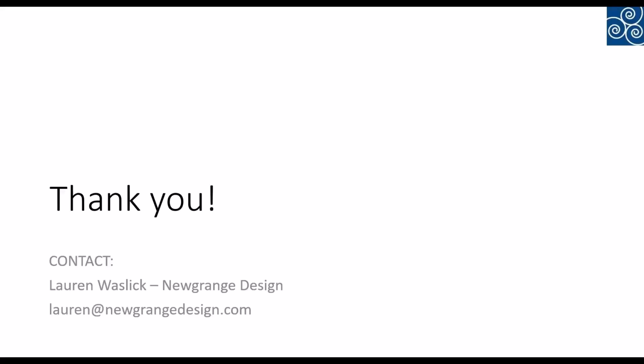What would be the smallest number of layers for a rigid flex design? So for flex, strictly a flex section, you can do a 1-layer flex. That's pretty common, 1 or 2 layers. Again, you can go 3 or 4 layers, but the higher the layer count, the less flexibility you get. In terms of the rigid portion of that, I don't know if I've ever seen a 2-layer rigid. If you're going to do a 1-layer flex, it would probably end up being a 3-layer rigid because you'd have 1 middle layer and 1 top and 1 bottom. But it can just go down to 1 layer with no problem. Those are very common.